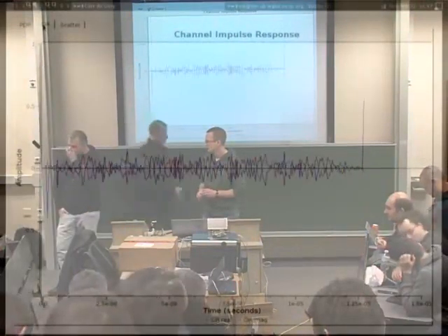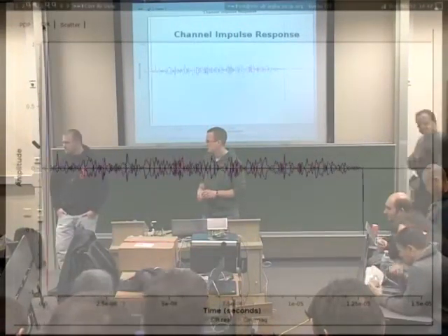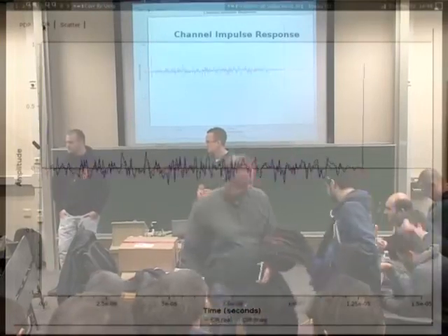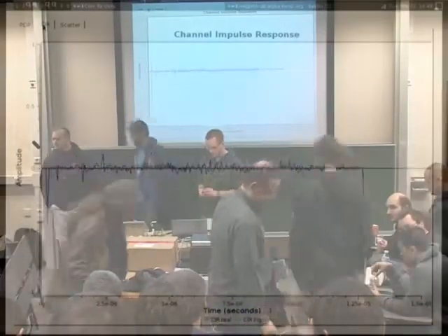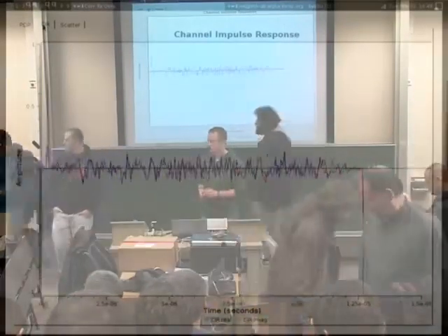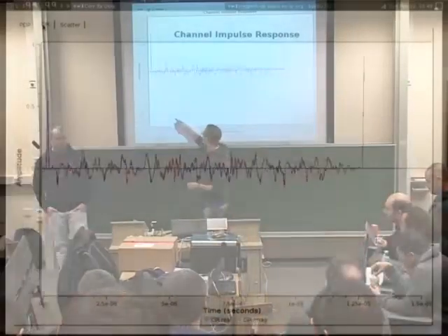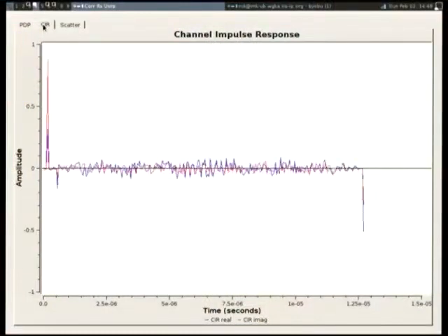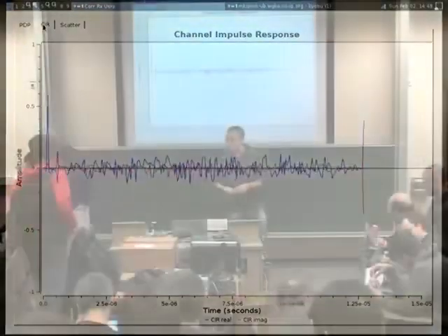And then we also have the hardware impairments model, which we use to simulate IIP3, IIP2, phase noise, quantization noise, those types of things, to try to model the hardware. Yeah, just an example. Actually, we have plugged in the channel model, and now we are sounding the channel model. This is basically how the channel impulse response is changing.